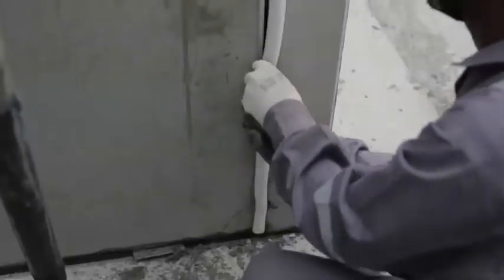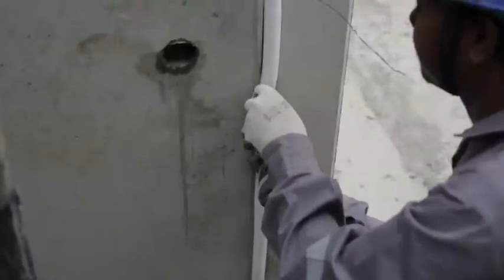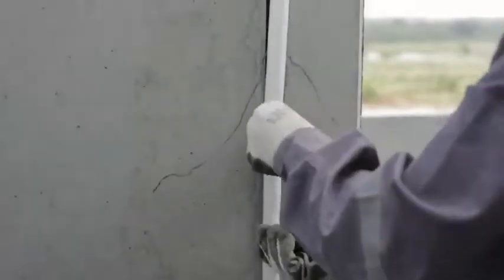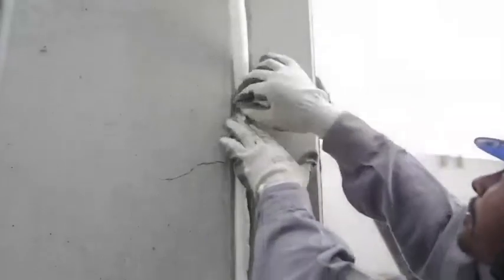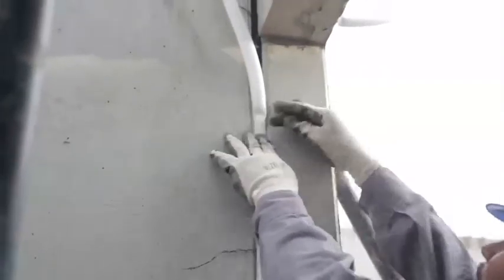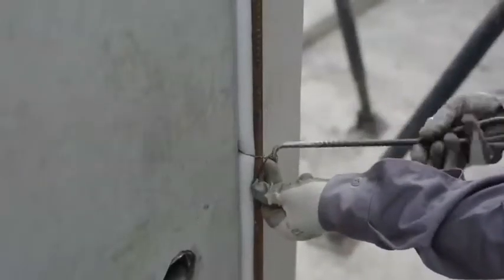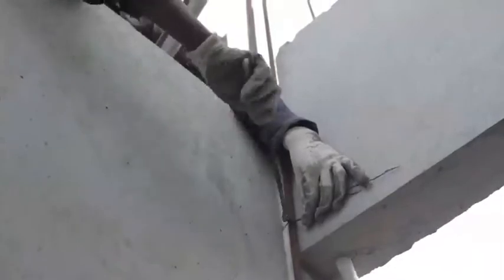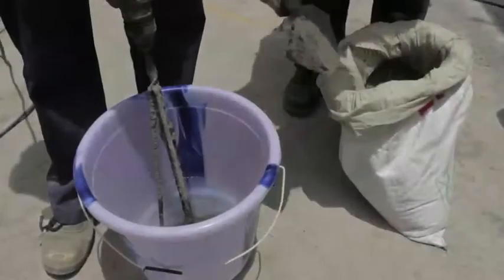Before grouting, all the vertical joints need to be sealed with Baker rods to prevent any grout leakage. Horizontal joints between slabs and wall panels are sealed with mortar to prevent grout leakage. The panel-to-panel joints should be grouted with approved material.